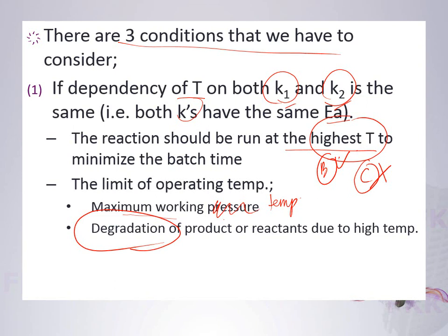Okay, so how to bring the temperature down? What is another parameter that you can actually set in your distillation column so that you can bring the temperature of your reboiler down? How to do that? Huh? Say it again. Number of stages.